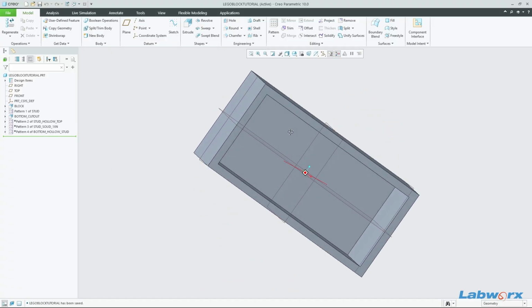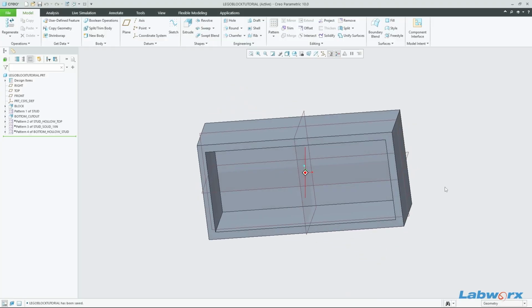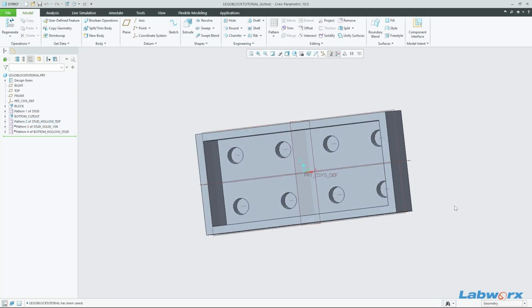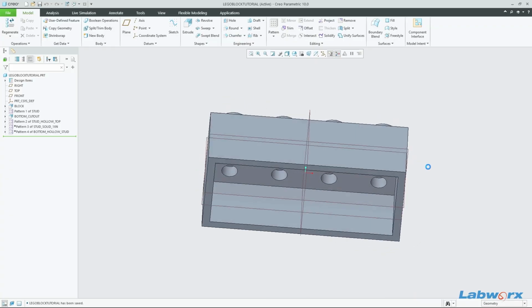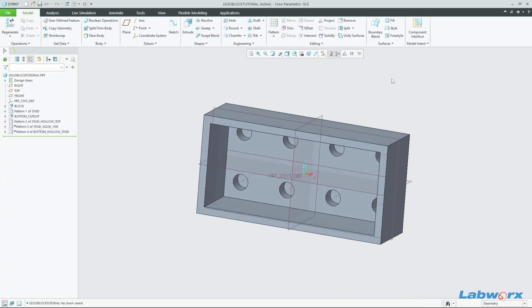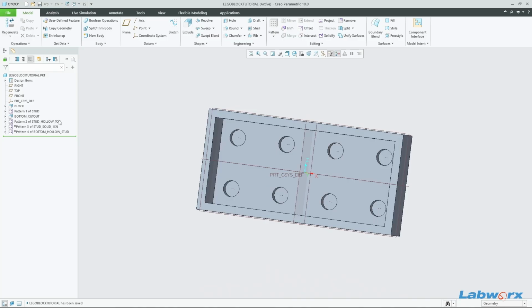Now that we've got everything working, and we've got all our features and patterns suppressed, we need to set our patterns to show and hide based on certain conditions. Our stud hollow top pattern is going to be displayed no matter what, so we can leave that on there, because it is going to be shown whether it's a 1x1 stud pattern, or 1 by something, or something by something. It's always going to be a feature that's shown.